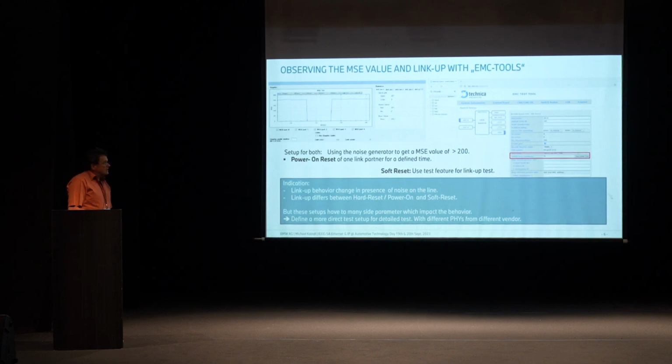Let's look at the tool itself. On the left, we see a value, the MSE test. We use an MSE value of 206, which in the past was our criterion for qualifying the 100BASE-T1 tools and setups. Here we have established a link with 206. I do a reset. Does it come up? Look at the time, look at the level, and it works.